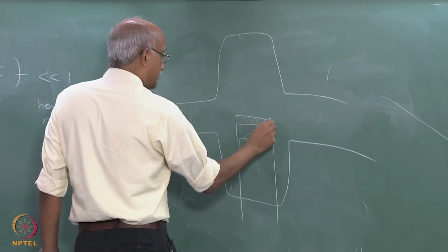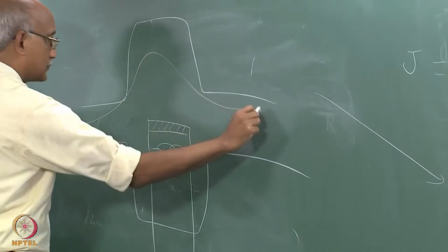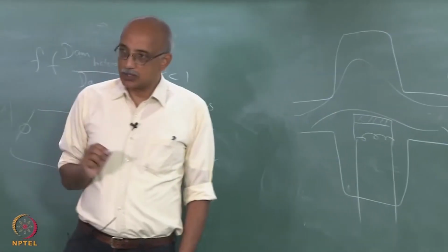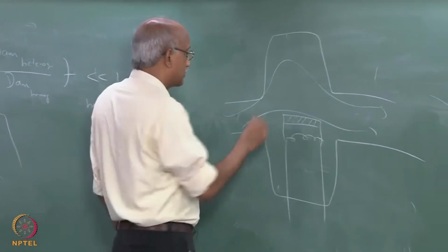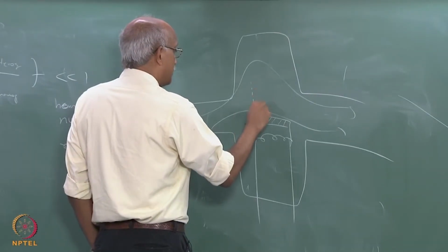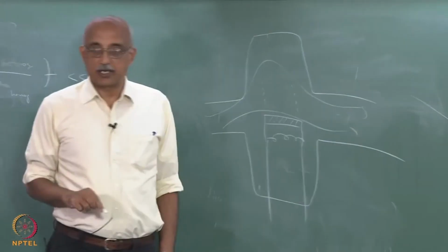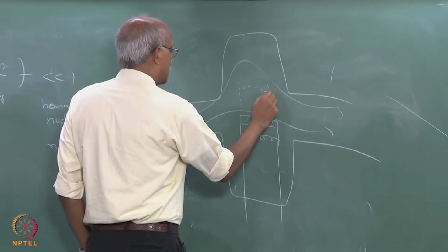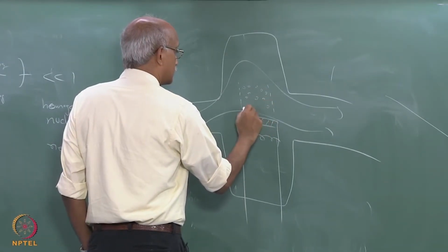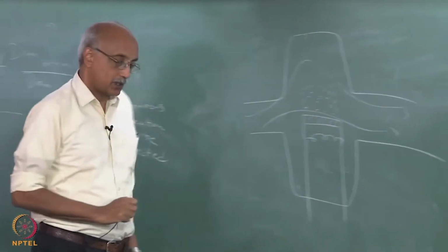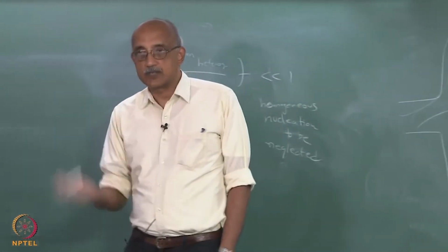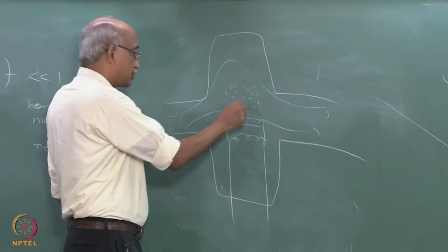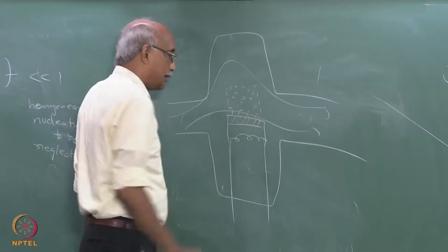and you have your wafer here, and the gas flow is like this. If you want to use this as an aerosol CVD reactor, the aerosols should, as far as possible, be formed in a region that is directly above the substrate, so that they will naturally, just by gravitational sedimentation, other body force effects, by inertial effects, drop down on the substrate and deposit there.